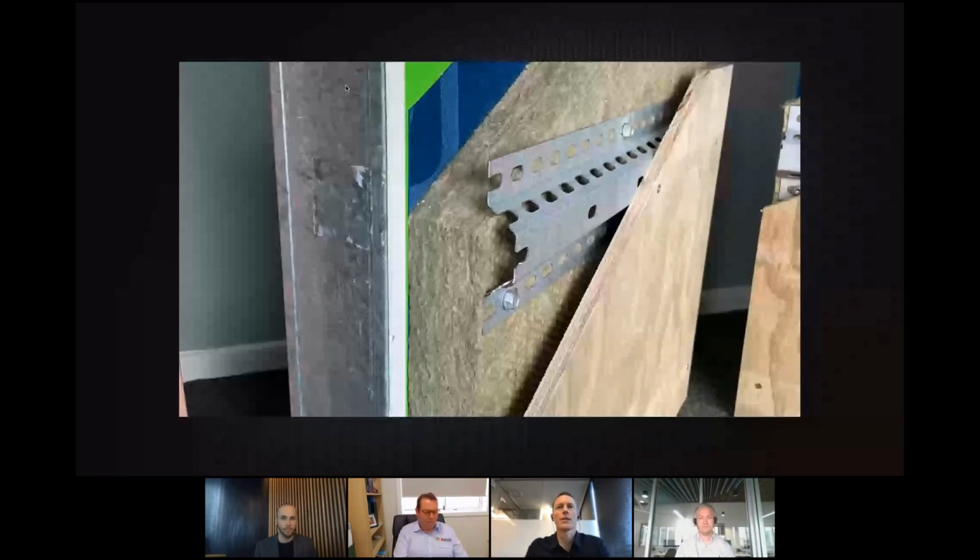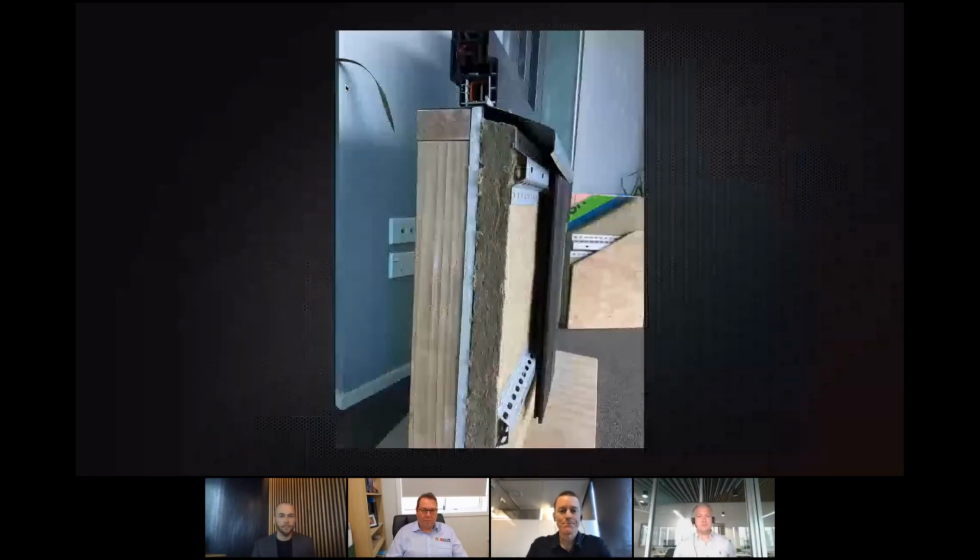And if that gets wet, as we've talked about today with the rainscreen cladding approach, where you can get some water through the cladding system and back to that next layer, if it does get wet, well, it's rock. It's spun basalt, candy floss basalt. Bugs don't eat it. Fire doesn't eat it either.